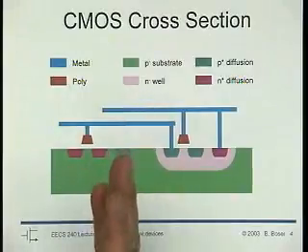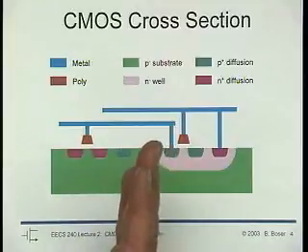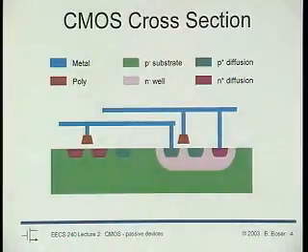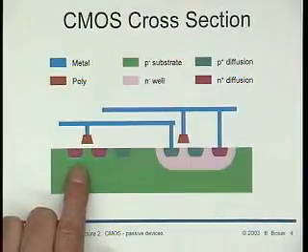And you got to tell SPICE that these diodes are there, and you got to tell SPICE how big these diodes are, because if they're not there, you may forward bias one of these diodes. SPICE isn't going to tell you about something that is not in the netlist, right? They are also capacitors, and most of the time we really didn't need them.